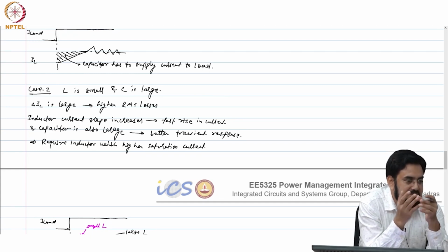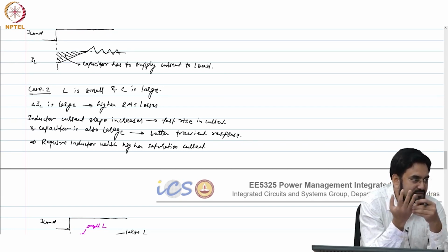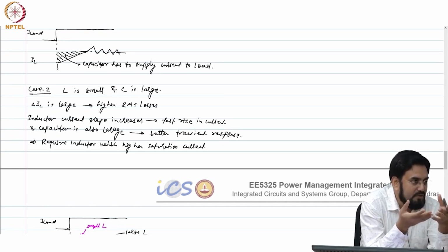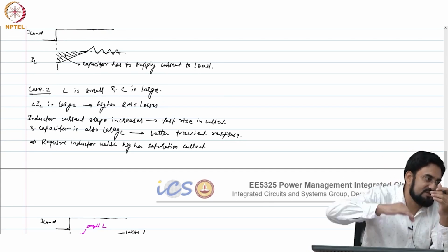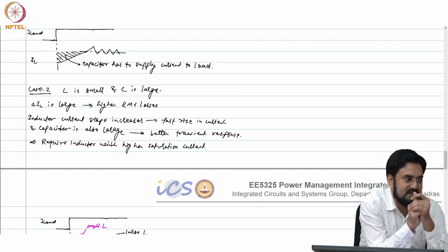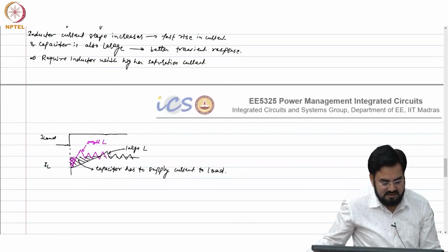So you pick the same series of the inductor. From the same series means they are manufactured using the same material, same core, everything. So use a 1 microhenry, then look at a 0.47 or half microhenry, and 0.2 or 0.1. As you reduce the values, you will see your I sat will start increasing and DCR will also start reducing. Okay. We will look at the data sheet probably in the next class.